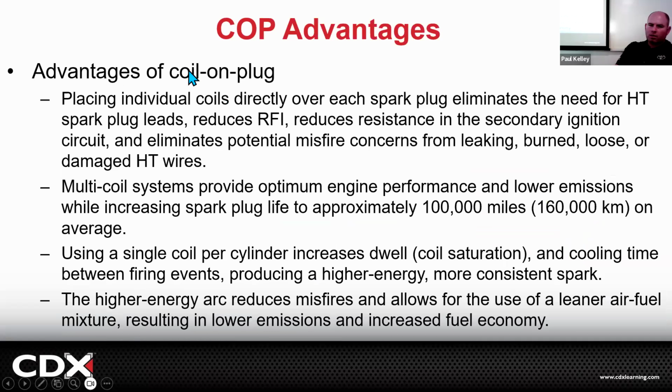There's advantages. It eliminates the high tension cables, eliminates the spark plug leads, eliminates the cap, the rotor, all that, and reduces interference. It's less resistance because it doesn't have long wires and multiple connections. It doesn't have as many concerns for leaking voltage, which means arcing, right? So if you have a spark plug wire on the top of the valve cover and it arcs, what if you have a fuel leak where it's arcing? In fuego, right? You could have a fire right there.